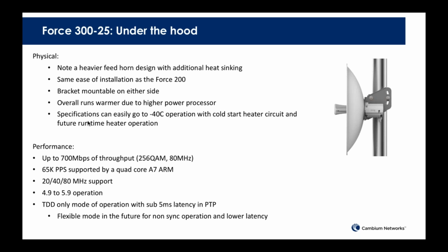But even with a 5 millisecond latency, because of the new design, new chipset, and new software architecture, we've been able to reduce our latency in the point-to-point down to an average of 3 milliseconds, even with the TDD operation of 5 millisecond frame size.